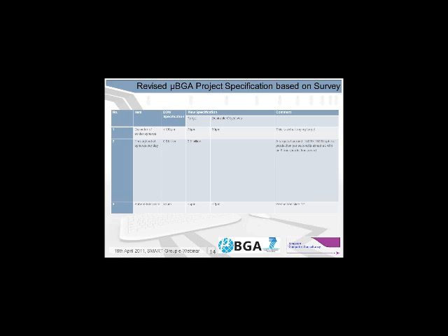We have a current, initial target of 5 microns, as there isn't quite the consistency required across the entire industry, but we are aiming at getting down to the original target of a 2 micron tolerance for the 50 micron and 75 micron solder ball diameters.